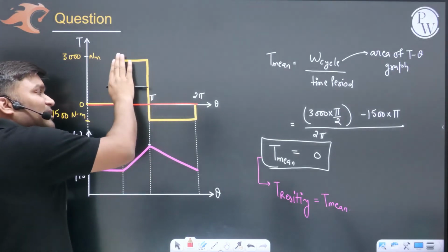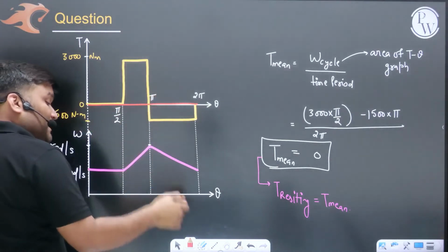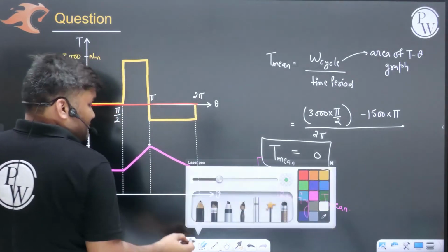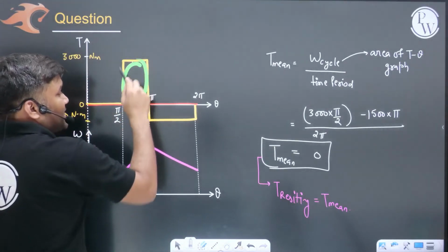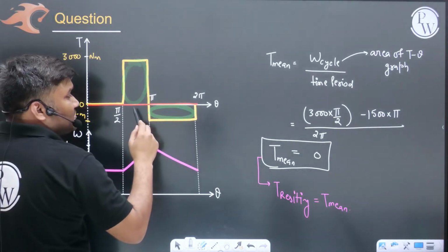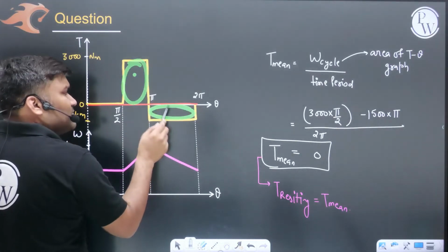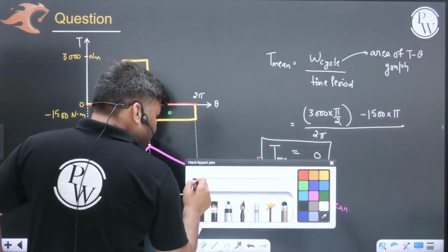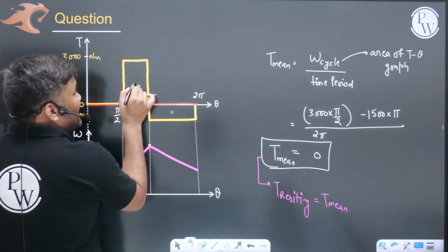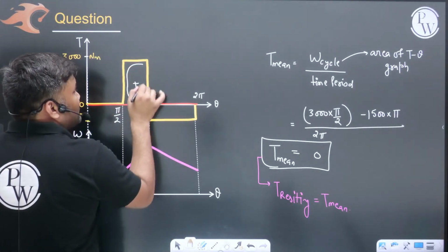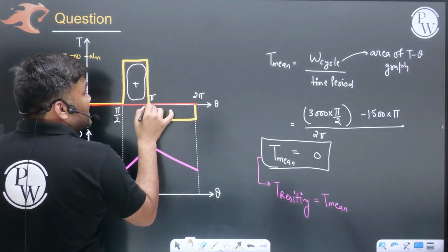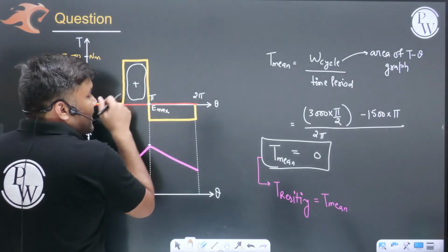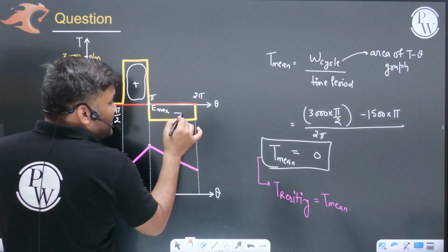Now, available torque is drawn, resisting torque is drawn. Now you can see the fluctuations. Fluctuations क्या नजर आ रहे हैं बेटे? Sir, flywheel will absorb energy here, deliver energy here. Either of them you can consider as delta E max. क्यों? Why I am saying this? Whenever flywheel will absorb energy, at this point its energy is going to be maximum. ठीक है? Flywheel will release a certain amount of energy here.